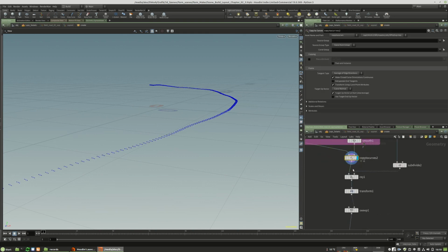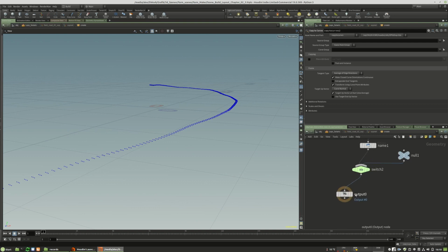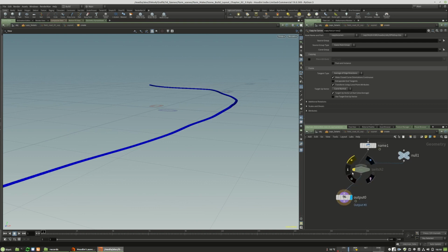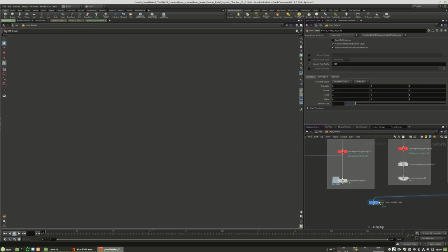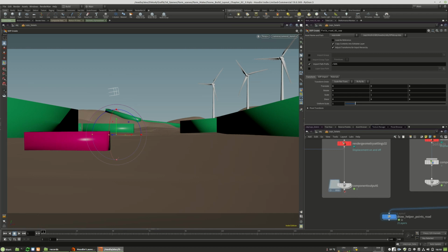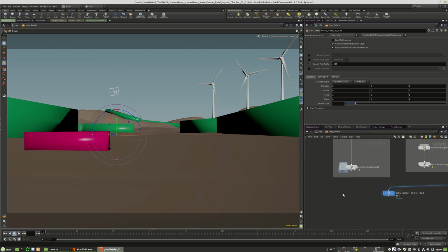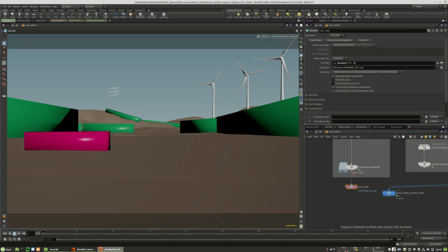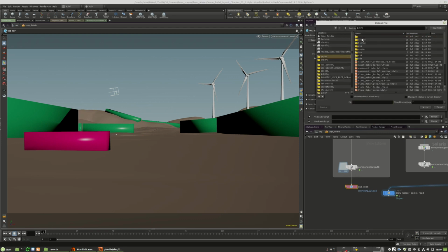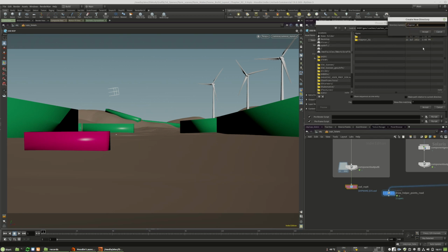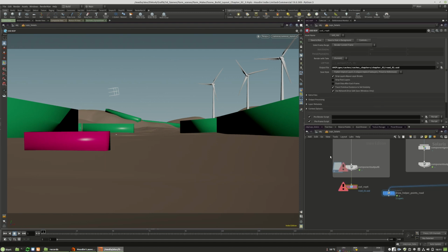Okay, so now the road gets built, and here we can deactivate that. Now the road is generated. We can go back in here. We will link it directly, or we can, yeah, bake it out with a USD ROP. So caches, go back, caches chapters, and we are now in chapter 02. Road cache or road 01 USD, and we will bake it.